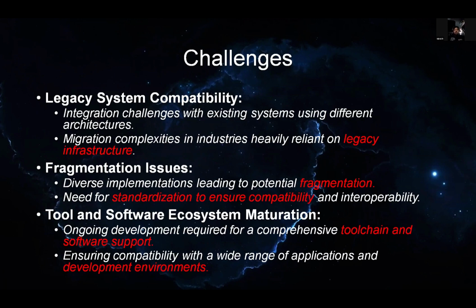Right. Now, when it comes to challenges, we have integration challenges. Now that this is a new architecture, we are going to see challenges when it comes to integration in legacy hardware and older systems. We're going to see people reluctant to migrate to something new because over the years we've seen ARM and x86 take up a large part of the market space, but with RISC-V coming in new, migration may be an issue. There's also fragmentation because, being an open source architecture, a lot of people will pick this up, making small customizations, and eventually we might see some incompatibility between multiple systems designed with RISC-V, which is where RISC-V International regulates this to make sure that compatibility is maintained.